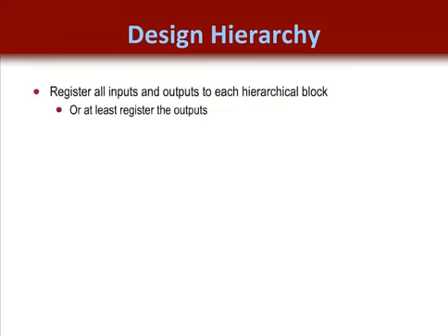Keep in mind that it is important to register all inputs and outputs to a hierarchical block when there is a possibility incremental design practices will be employed. You may recall that incremental design allows a designer to maintain the place and route solution on a module basis. The benefit is that it saves development time when you have found a result that meets your needs. So implementing the design each time now becomes implementing just the components you are not happy with.